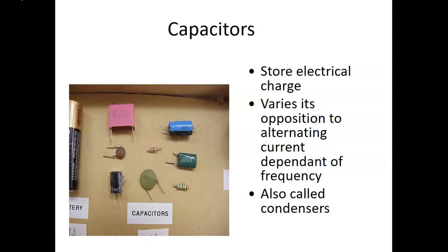So can we see how they look, or are they hidden? Capacitors? You don't want to get in here with one of these. The voltages that these things deal with would be enough to fry somebody. It's bad enough that these things store voltages, and if you don't discharge a capacitor before working on it, you're going to hurt something.